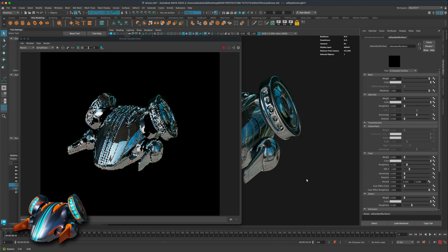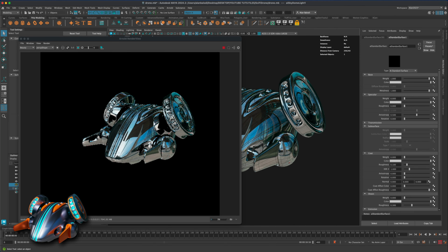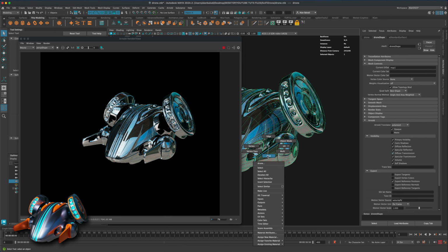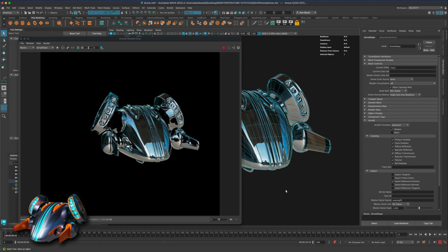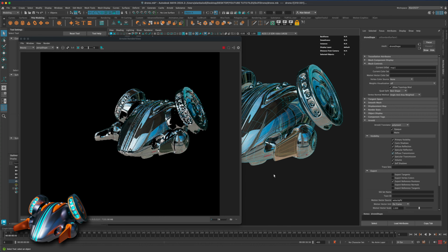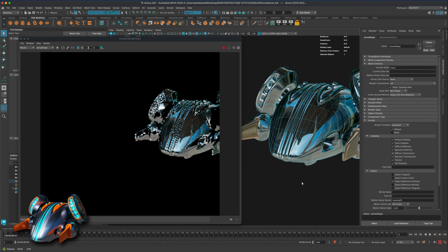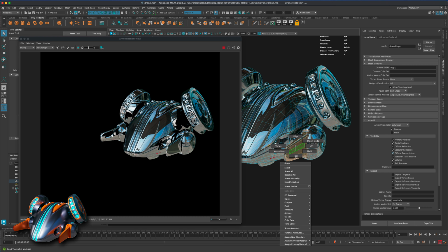And then one more thing, if you wanted to do multiple materials for the same shape, you just simply select the pieces that you want to apply a different material to. So if I hold the Shift key, I can grow my selection, for example. And let's say I want this part to be a different material from the rest, right? What I can do is I can just simply right-click, apply a different material to this, right?